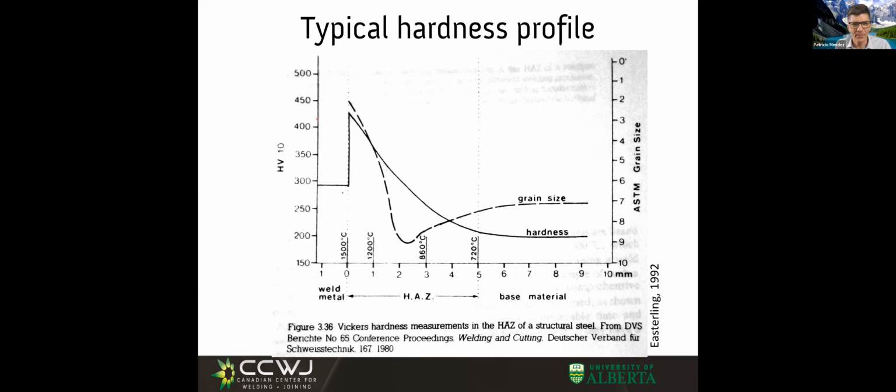And this graph is kind of ambiguous because they went from indicating the grain size of the ferrite, getting smaller and smaller, and then all of a sudden they're indicating the grain size of the primary austenite grain, which is huge. But this is primary austenite grain in this part of the curve, and this is ferrite grain size in this other part of the curve.